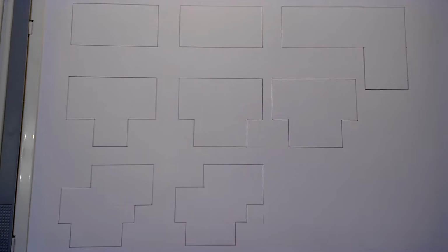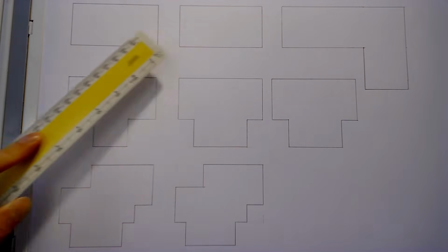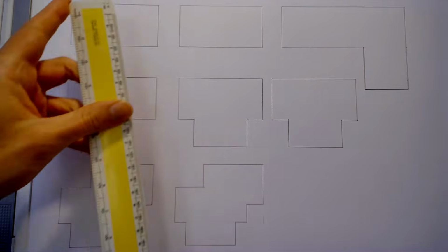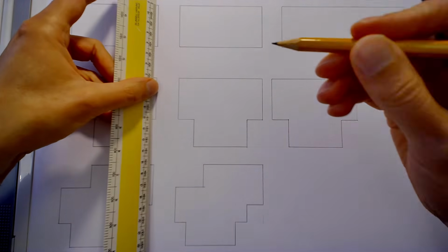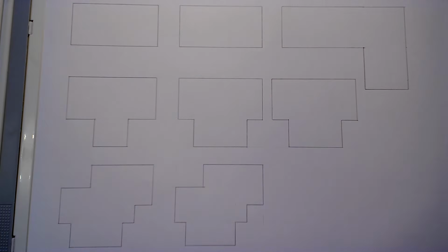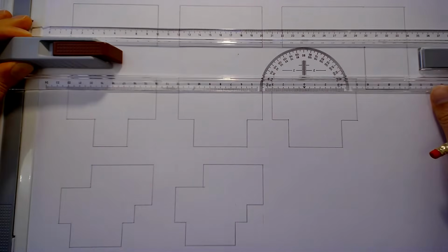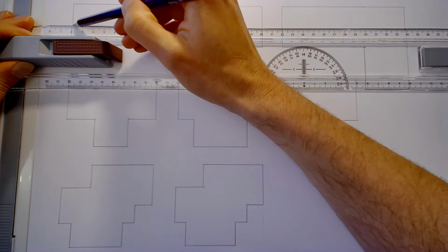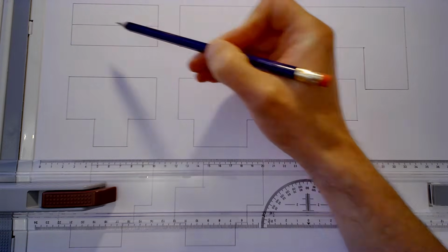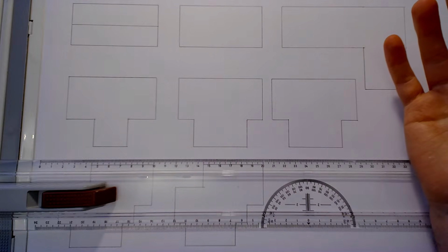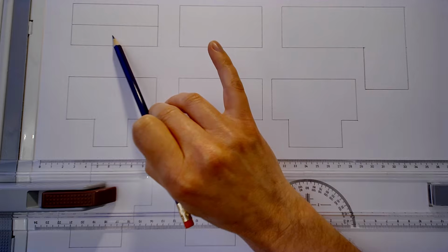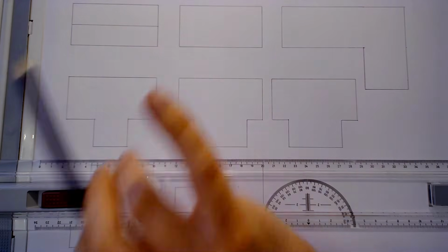So first of all, we'll start up in the top left hand corner by here, and what we have is a basic oblong. So really we've got two options, and what we're going to do is have a little look at, first of all, just putting a line across the centre, and this would form a ridge, and what we would have here is a gable end at either end of the building. So no other sloping sides, but just two gables, and then your slope up there and slope down there with the ridge in the middle.